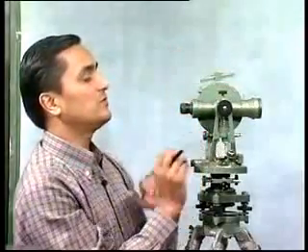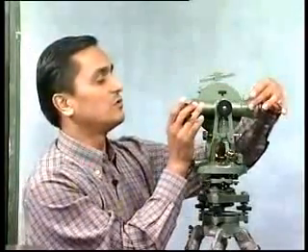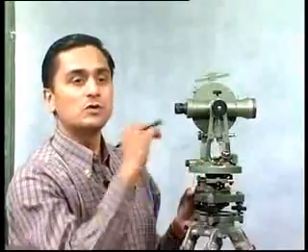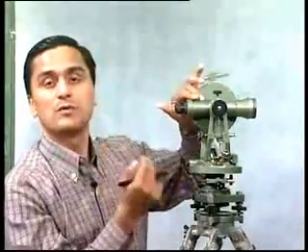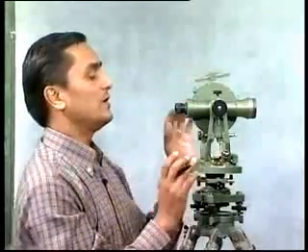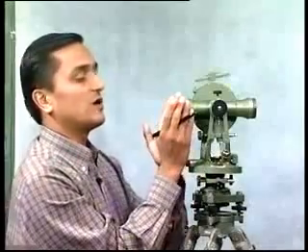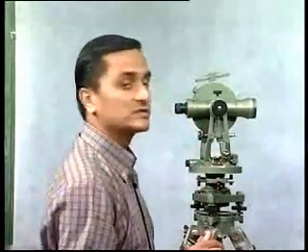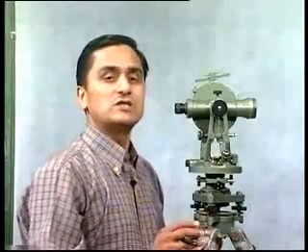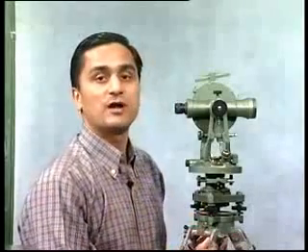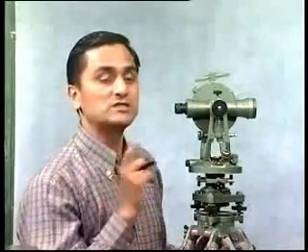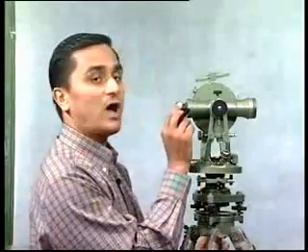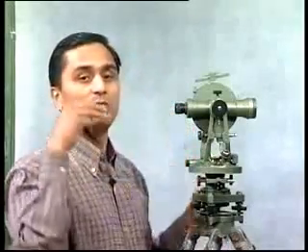Now here also, in the case of the telescope, we'll look into the optics of the telescope next time. But today, this part of the telescope is called the eyepiece because I keep it towards me and I look through this. And mostly, whenever we set this instrument, we should ensure that the instrument is set in such a way that the eyepiece is at the height of my eye or the eye of the observer.